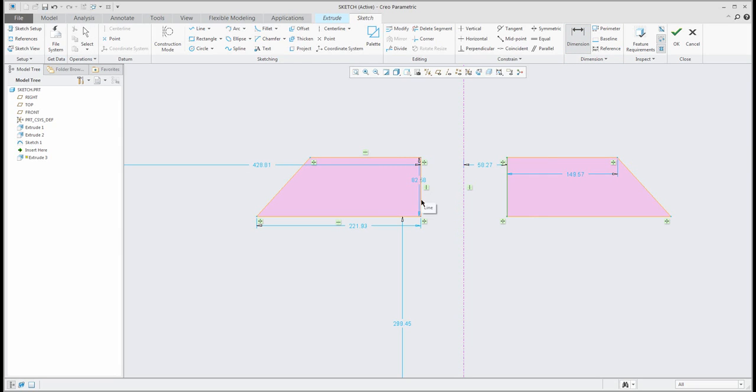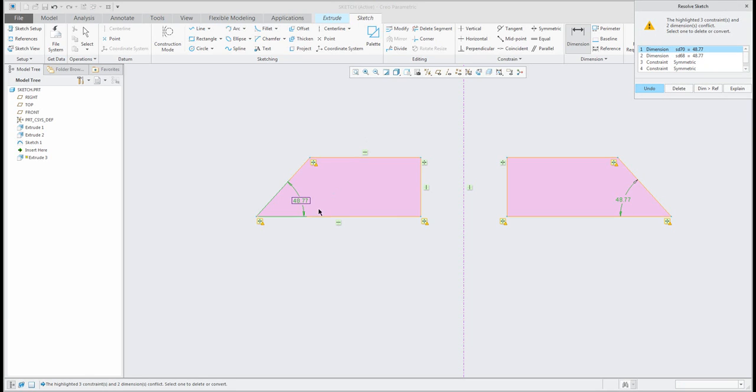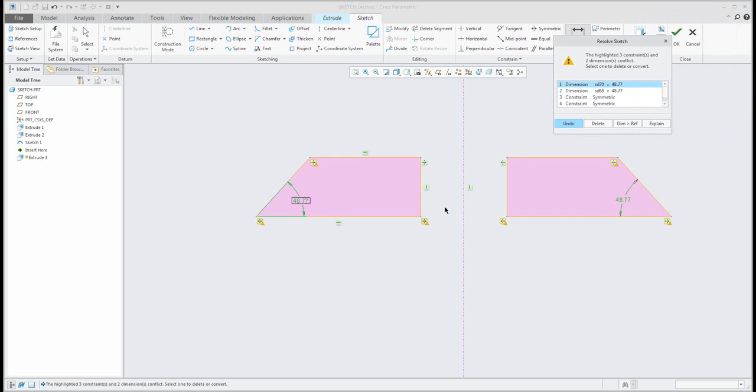You can select the references, and you will see the dimensions, or you can continue and create and confirm with the middle button. Yeah, so select one reference and confirm with the middle button and set the dimensions, for example 150, or select more than 2 references and confirm again. What's happened right now? On the left side and right side I specify the same dimensions. Sometimes it's necessary to see both dimensions on the left side and right side, but the system checks if you create unnecessary dimensions.